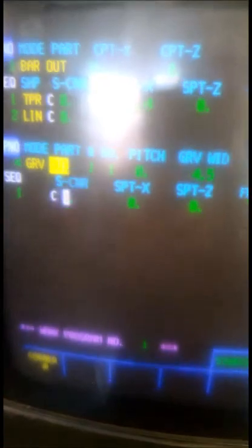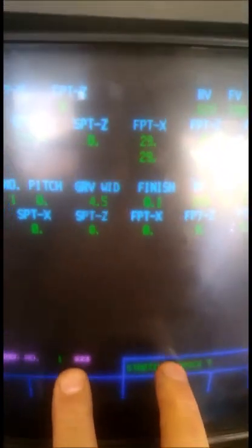Okay, so starting corner. So with these trapezoid grooves, the starting corner refers to both of the top corners, and the finishing corner refers to both of the bottom corners. There's no way to set them independently, and I don't need anything on that. Starting point X will be 29, where we turned that down to, so 29. Starting point in Z will be 0.84, so that back face there, 0.84.